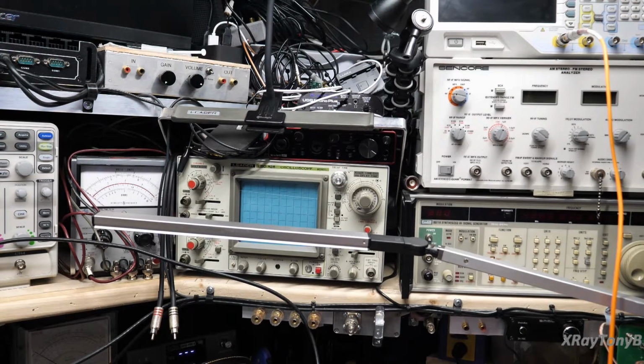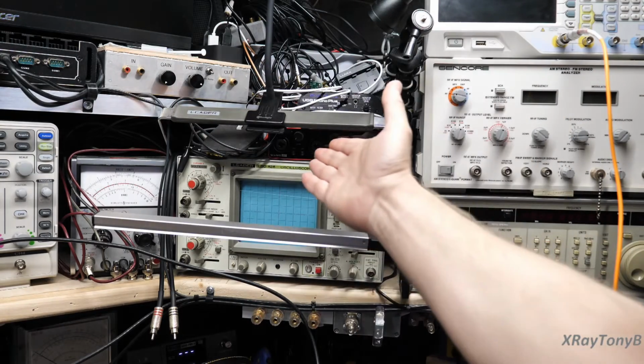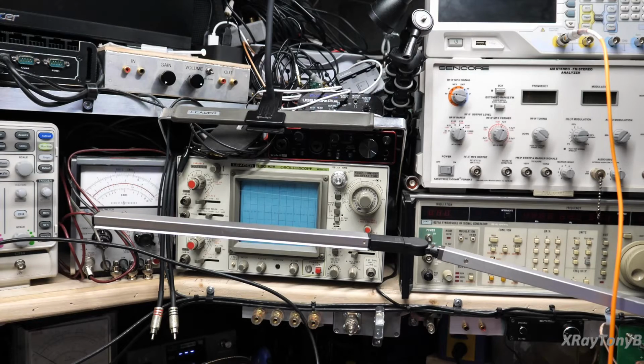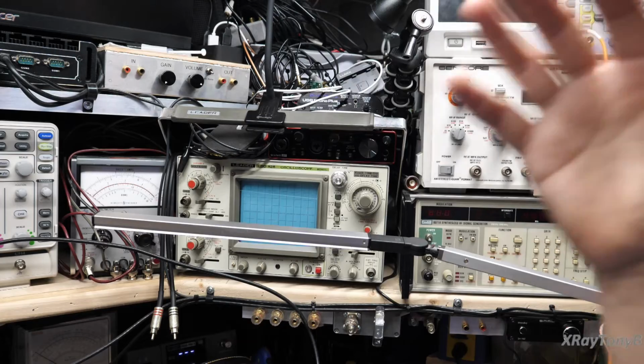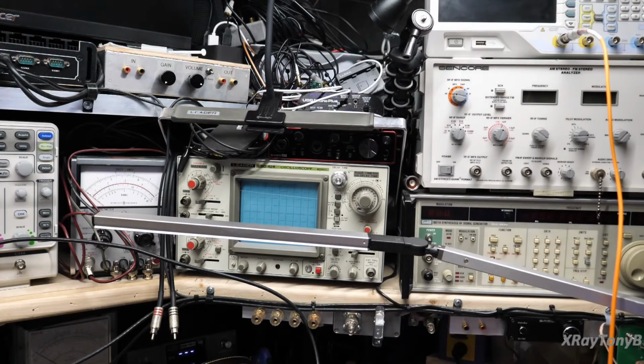A lot of computer-based sound cards are not that good, although they can be very good. It's like anything else. The software requires setup. You have to get everything to work. The other thing, you have to be very careful when you're using computer software. You can't just feed your speaker terminals into this. You will have to have some sort of attenuation, protection so that you don't overload your sound card and destroy it.